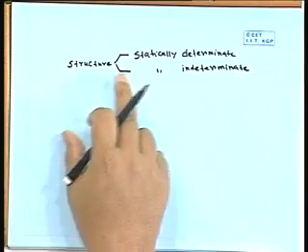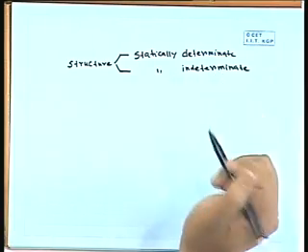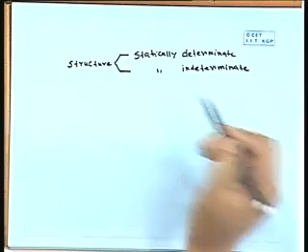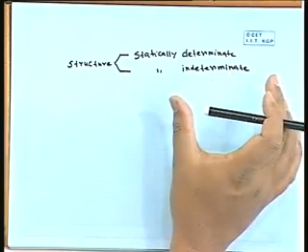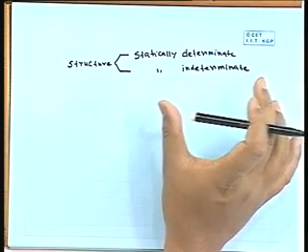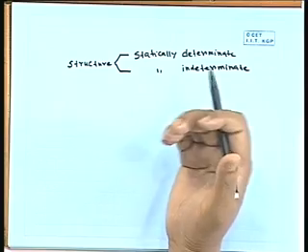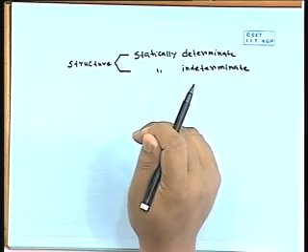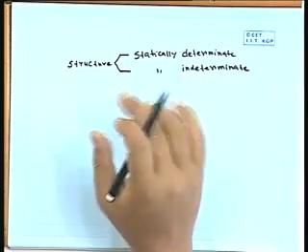So it is just two groups, statically determinate and statically indeterminate. The division is made basically on the idea of the equations of statics. Any problem has some equations of statics. If we take a three-dimensional problem, we will have 6 equations of statics. If we take a plane problem, it will have 3 equations of statics.